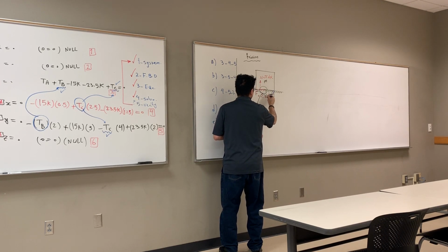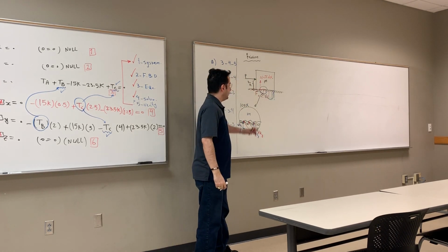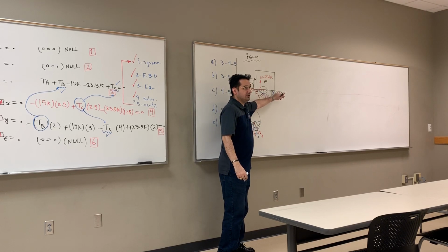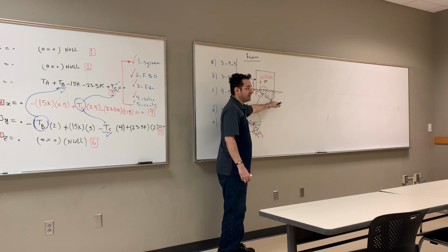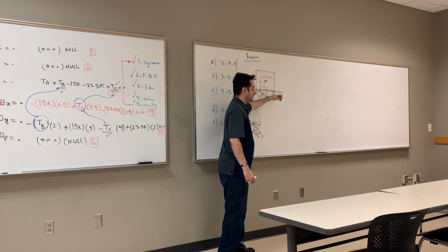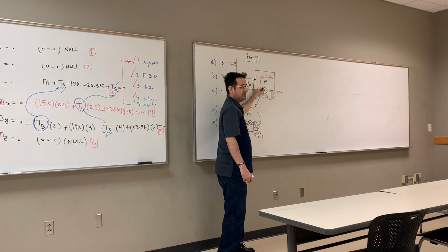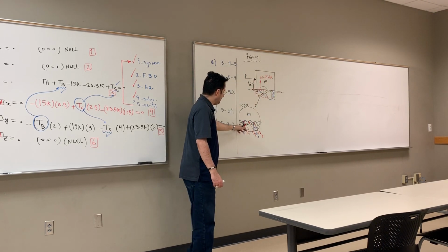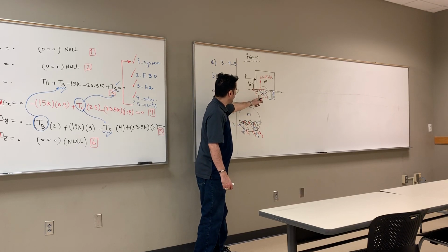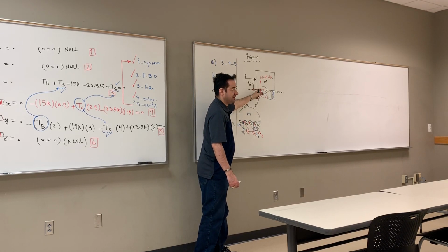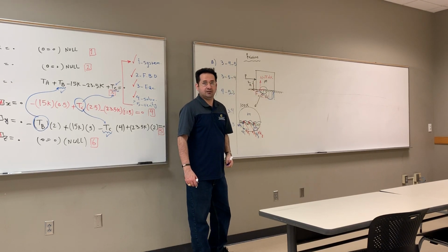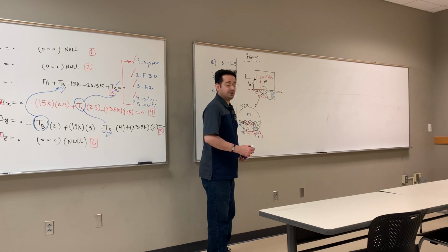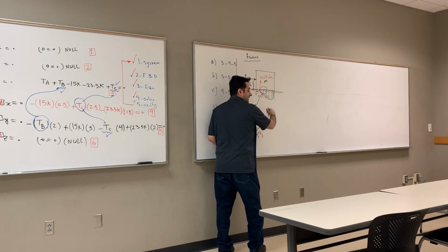In fact, it's a distributed load. The value of friction on the surface at each point is a distributed load. It's very small here, and it's almost maximum somewhere here, right? Because they already start to tip over, right? So here we have more friction than here, right? So in fact, if I want to take the resultant, sum in the x and y direction, and say F and R, where should I put this resultant? One-third. Yeah, if this was a triangle, yes, one-third.